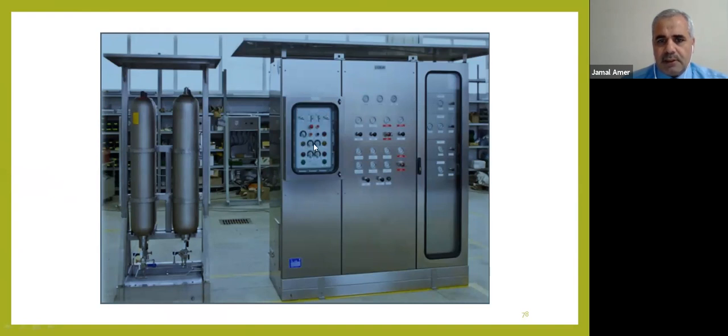As we see here, gauges and push buttons, and here the accumulator. We also have a pump on the other side of the panel. This panel is used to operate the hydraulic valves on the Christmas tree, either the downhole safety valve, or the choke valve or upper master valve, if they are hydraulically operated. They get their hydraulic oil pressure from this panel.